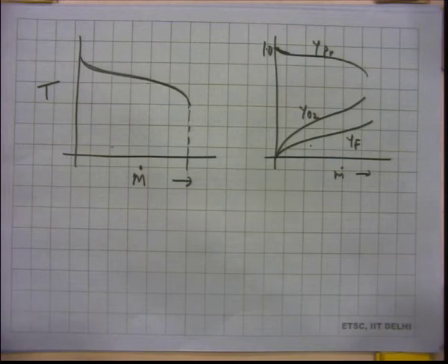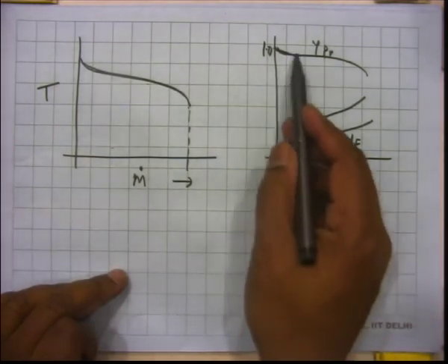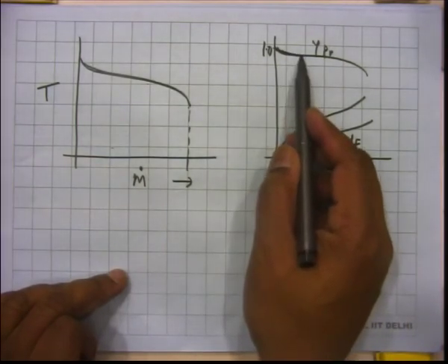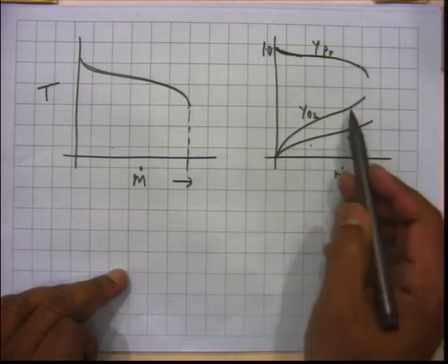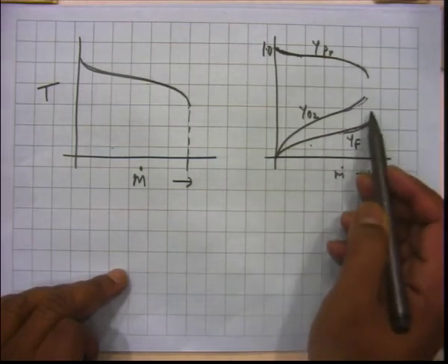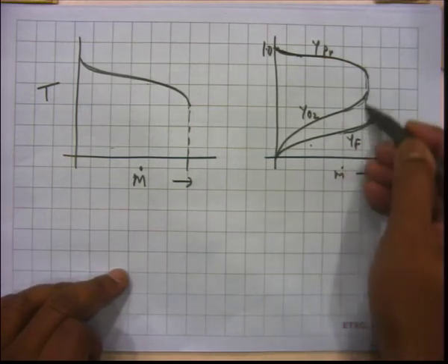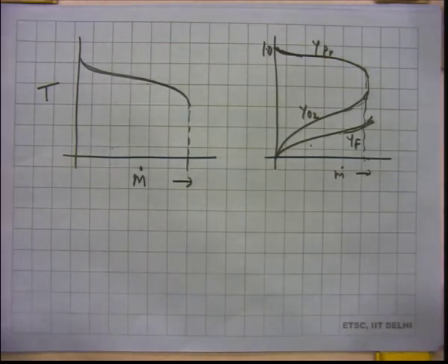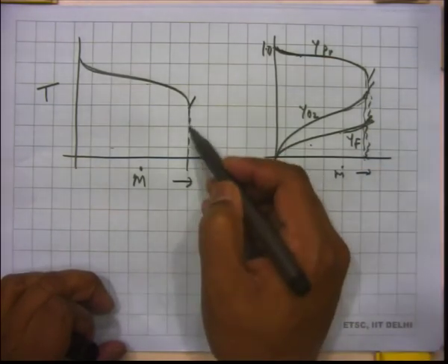This is not the inlet mass fraction. Inlet in any case does not have any products. So, as you increase m dot, you see that Y products is coming down to some extent, and finally it drops abruptly, and Y O2 and Y fuel just shoot up towards the end, for this kind of value of m dot. So, it means that there is blowout happening around this range.